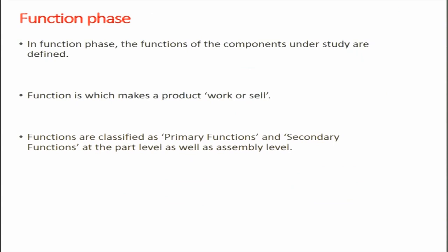Now comes the function phase. Function analysis is something that distinguishes and differentiates the value engineering technique from all other cost reduction or improvement techniques. So, in the function phase, the functions of the components under study are defined. As I said, the function of a product is something that makes it work or makes it sell. Functions may be classified as primary and secondary functions, which is all mentioned; I am just recalling those things.